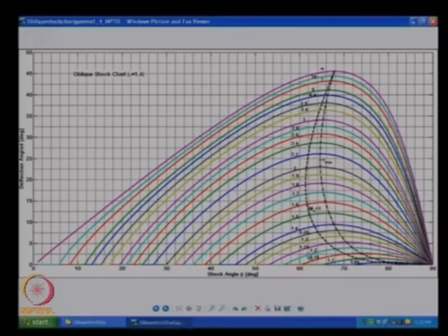These values written here 1.1, 1.2, 1.4, all this up to infinity, Mach number infinity, everything, it seems to be an inverted U shaped curve, which is for every deflection angle, let us say I pick 10 degrees and I go for say Mach 2, I could have an angle of the order of 39 degrees or I could have an angle of the order of 84 degrees or so.